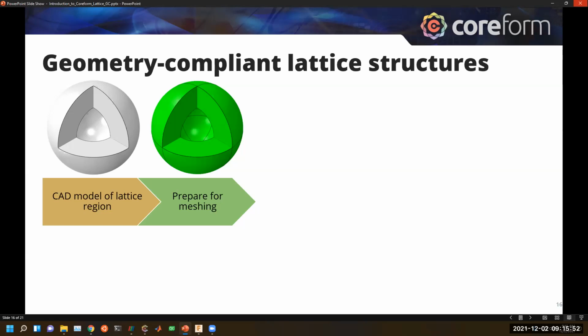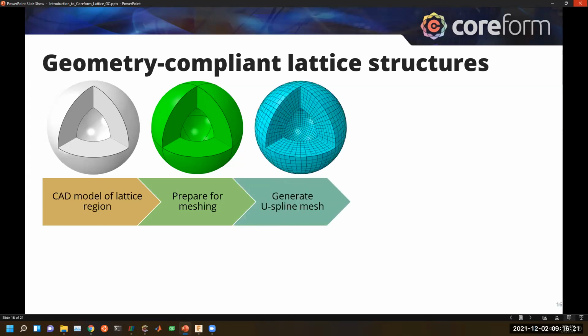To then prepare that CAD model for mesh generation. So you might do things, in this case, we're going to build a hex mesh. So we web cut or partition our geometry to permit a nice structured hex mesh. You might also do things like defeature or use virtual topology, compositing of surfaces and curves to ignore certain features to be able to get the layout of mesh elements that you want.